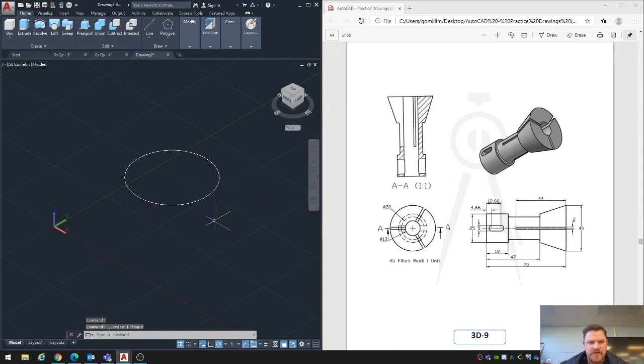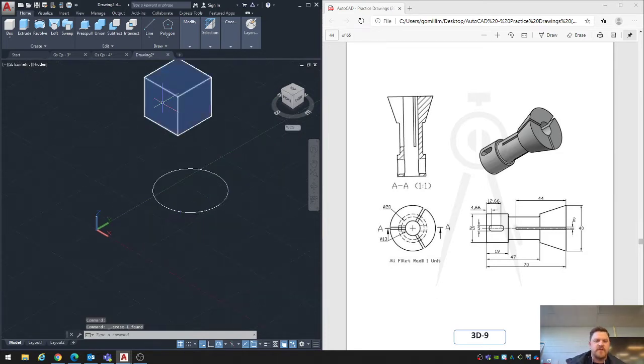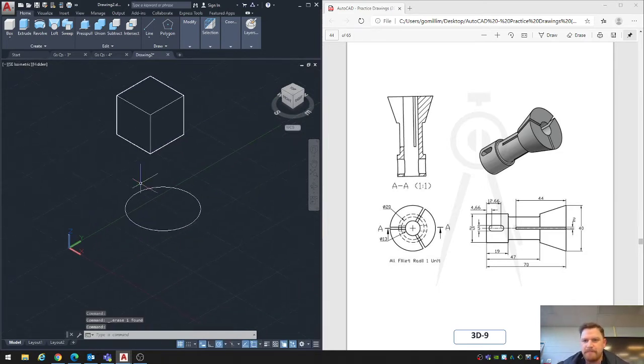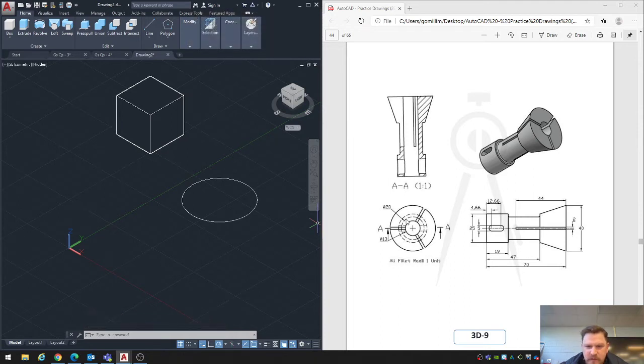Let's just copy paste this box up there in case I need to draw a circle on another face. So then it comes down into another shape here, which, based on this view, is 20 diameter. So it goes from 40 diameter to 20 diameter here. This side actually looks like it's 25. I wonder if it's 25. Let's see, oh yeah, so this inside is 20. So that's the inside cut, I think.